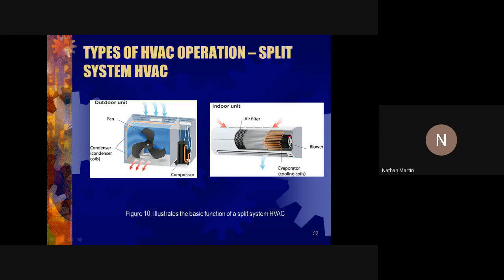So by manipulating the frequency, similar to what a VFD, variable frequency drive, does, they are able to control the speed of the compressor, right? So you have a continuous feedback loop. Because there's no time with the inverter type where the compressor is shut down altogether and has to start back up, as you'd run into the starting current issue.